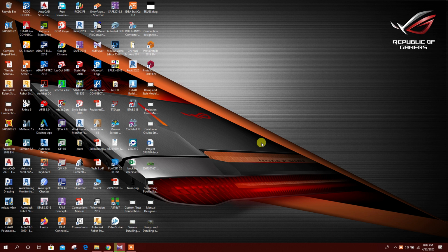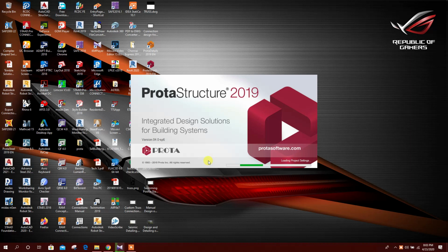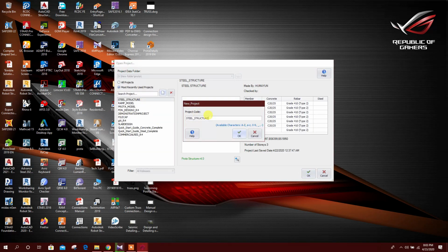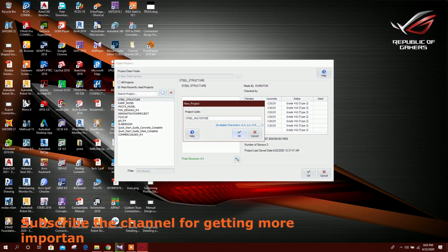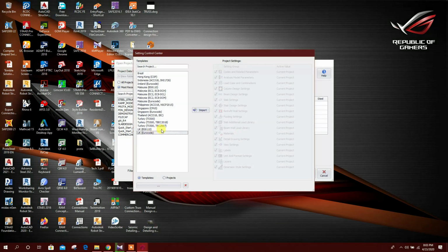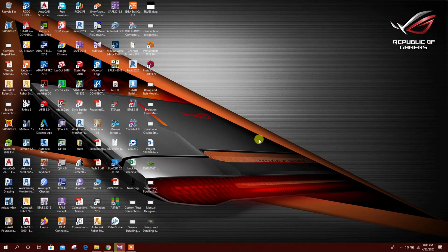Bismillahirrahmanirrahim. Dear viewers, today we will design a multi-storied steel building in Prota Structure. So let's start. Click on new project, steel structure, steel multi-storied. Click on OK. We will go for Eurocode.